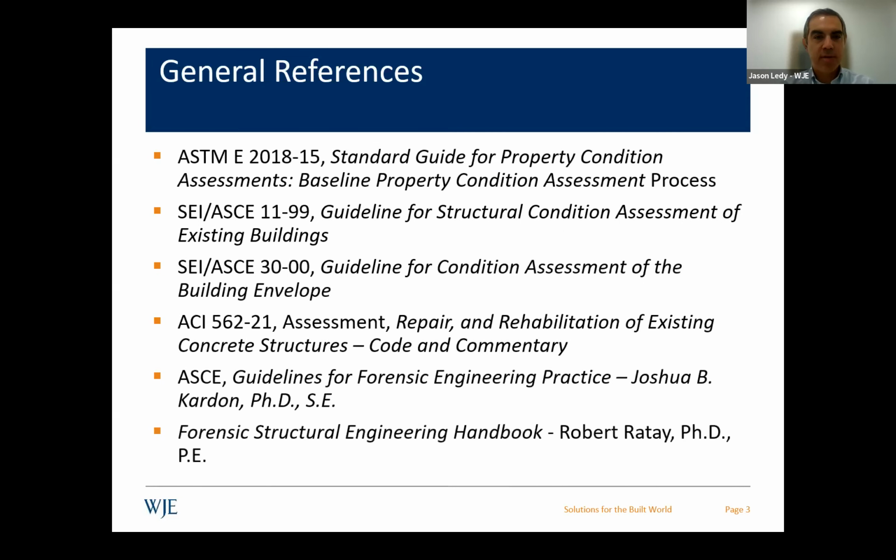Below is a list of references that may be helpful. Several ASTM and ASCE documents, guides for property condition assessments, guides for structural condition assessments, guide for construction assessment of building envelope, and then ACI has a concrete specific guide, which is repair and rehabilitation of existing concrete structures.